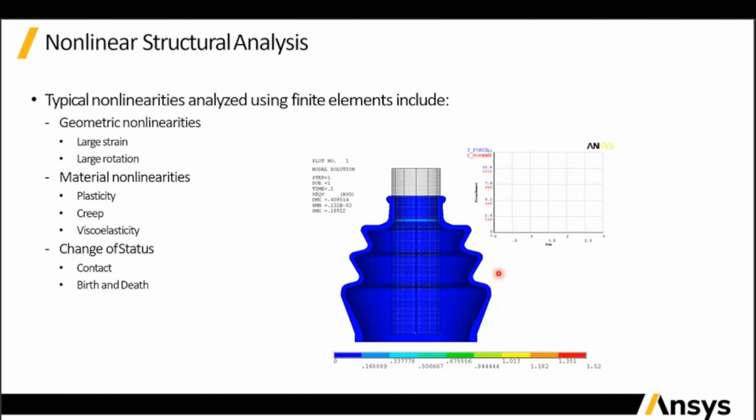The causes of the nonlinearity may be plasticity, as we took the example of the mild steel graph, right? Once you keep on loading the material, from the elastic zone, your material enters into the plastic zone. So this is how material nonlinearity takes place, or one cause is plasticity occurring in your material.